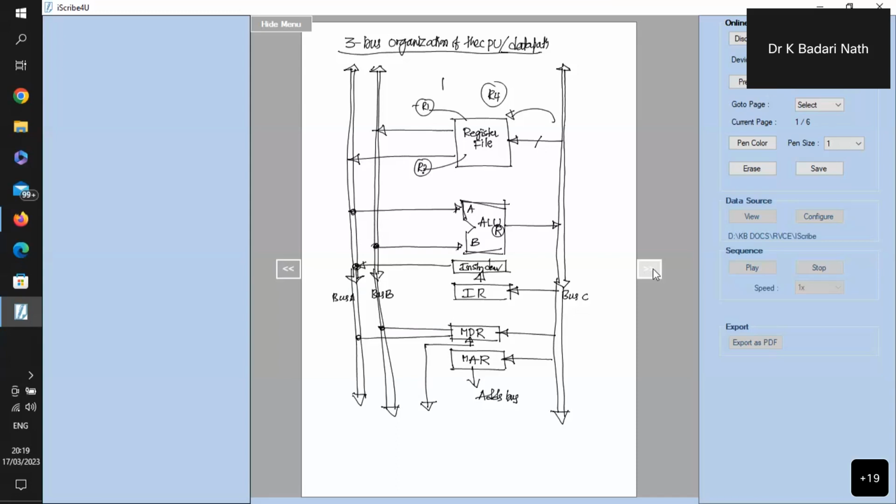Now, we will consider a program counter, the PC. The PC will generate the new address: the existing address will be taken, added to, and written back to the program counter. Instead of using the ALU for adding 4, most processors nowadays provide a separate incrementer.